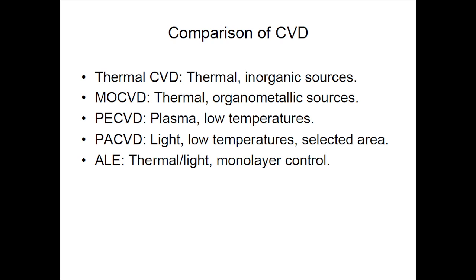And the atomic layer deposition case. Inorganic sources will be used for thermal CVD, and for MOCVD, again thermal energy will be used, with organometallic sources as the sources to deposit.